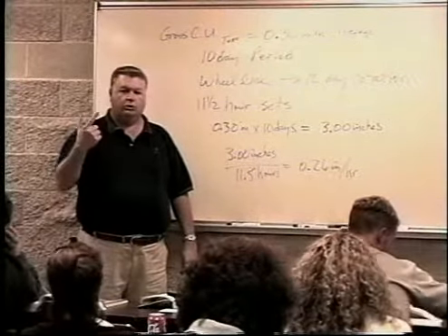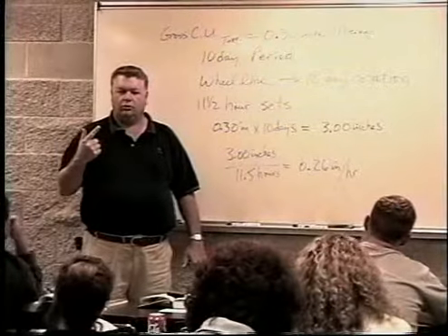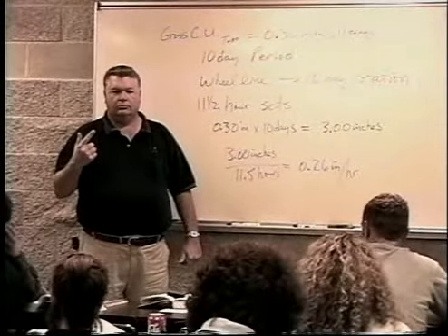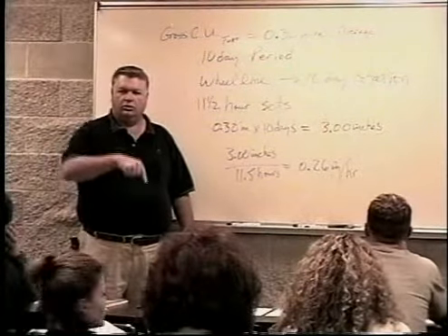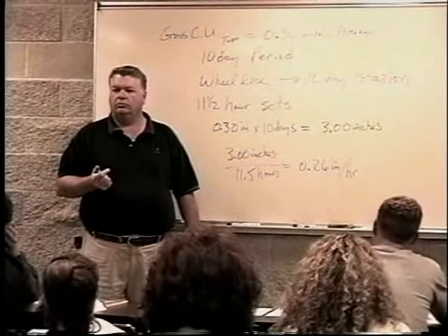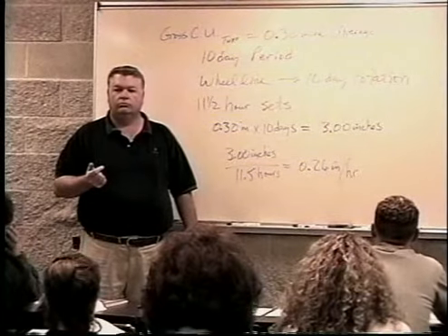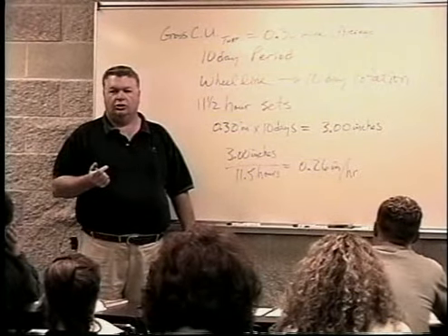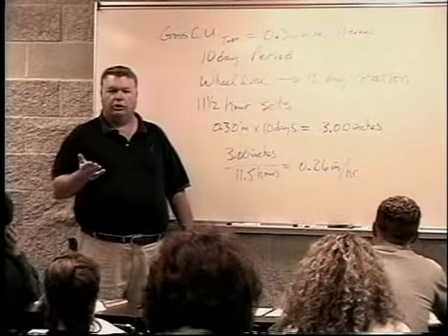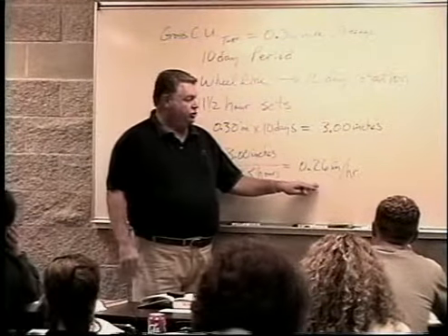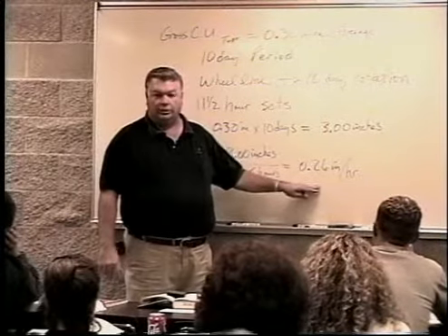Now we have to check for one more thing in this process. What is it? What's the other major concern we have besides our application rate? With water getting into the soil. The intake rate, sure. We have to make sure that the soil can intake the water at this rate.